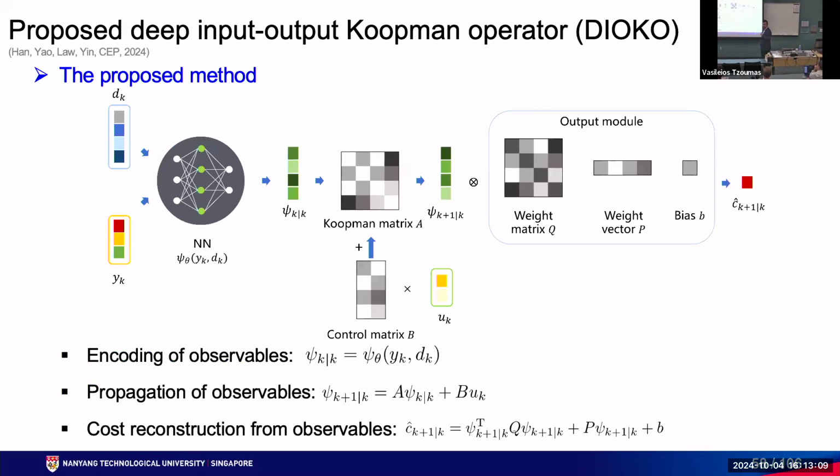Okay, this is the idea. We use a linear model to forecast the future information. Now we have a linear model, one step closer towards convex optimization, but not enough. The cost is still non-convex. The economic cost is nonlinear. How about we use a quadratic cost to approximate the nonlinear cost expression in the original coordinate? Now we have the flexibility to lift the state vector. And how about we just use this lifting function and we construct a quadratic objective function, right?